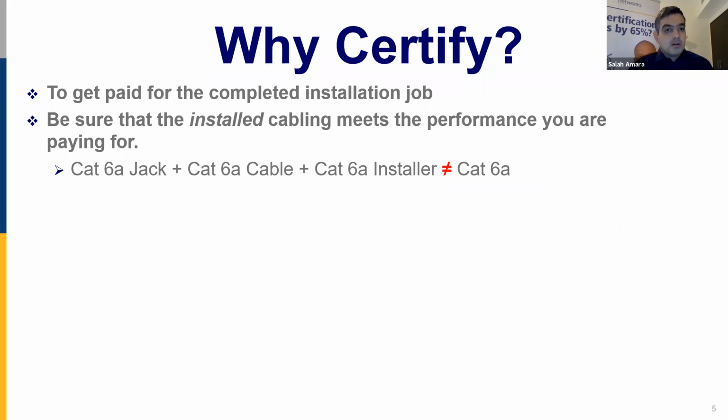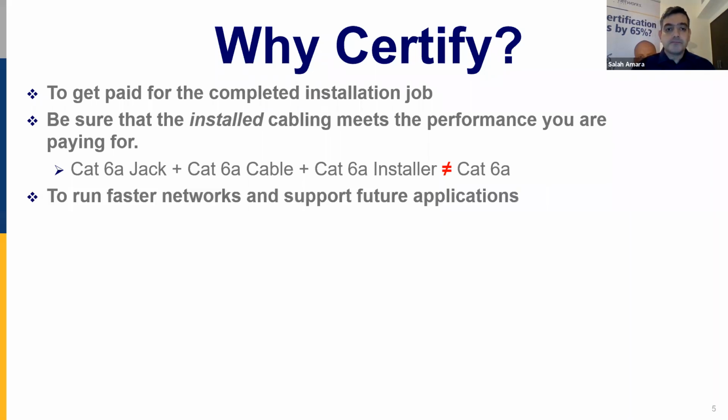Imagine that you are an end user or a consultant. You would not accept paying for a Cat 6A system and in the end getting the performance of Cat 5e, because you are wasting your money. So it's important not only to test as a manufacturer, but to test the installation once it's completed, once the cable and jack are terminated, to make sure that the installation has been done properly, and then we are testing a complete system.